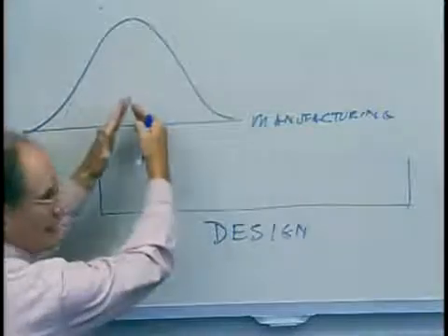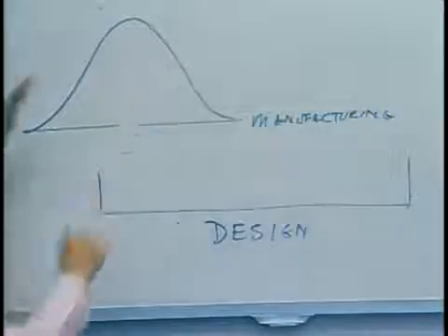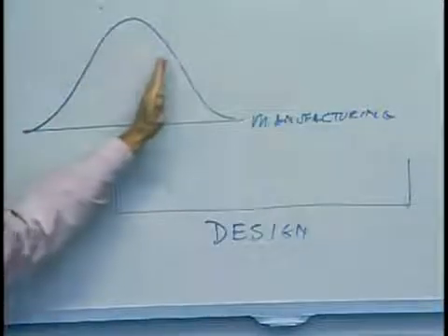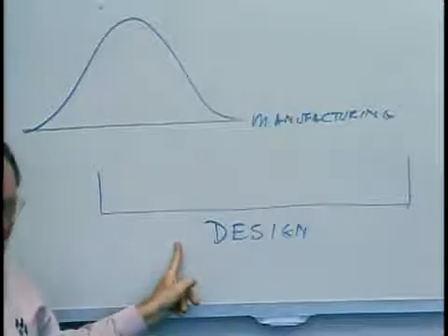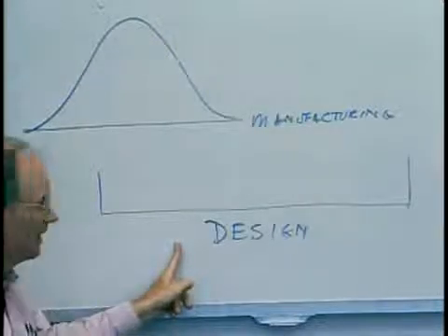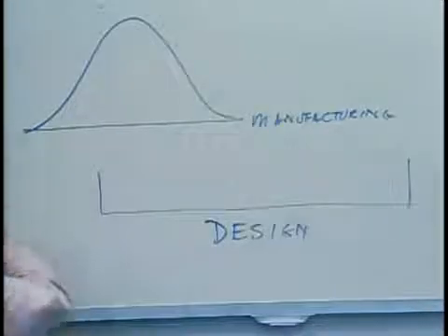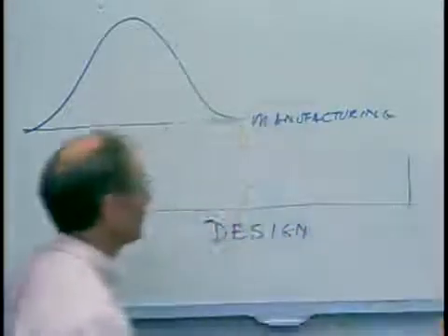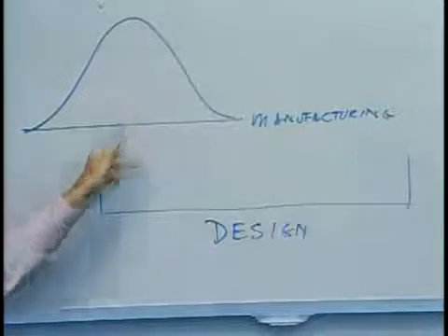I can do better manufacturing, I can center it. I can do worse manufacturing, I can buy new equipment, I can change this all the ways we've talked about. I can also go back to design, or start with design and say, you know, this part really isn't that important. This window could actually be here. And if I move the window out there, look at how the process capability just changed.